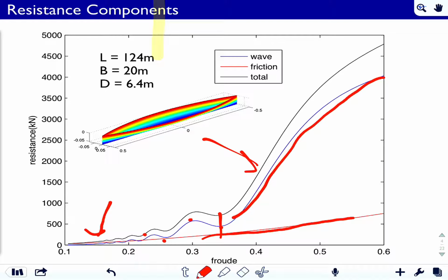And it's right around here that we assign a rough barrier to the top speed of a displacement vessel, because at that point the incremental power needed to get a higher speed is so great that it's not economically efficient. It isn't a hard number, but it's right around Froude number 0.4 as an approximate back of the envelope calculation, and that corresponds to a speed to length ratio of about 1.3.